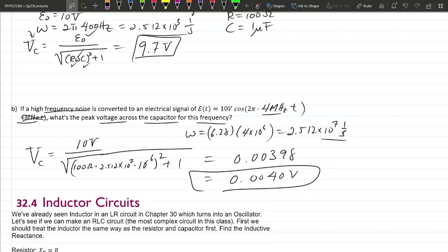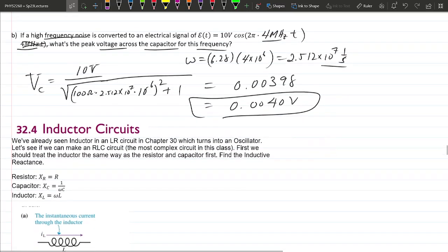It's used in every one of your devices, so that's why I want to make sure that this example is clear. Any questions? And if you did this with a high pass filter, the opposite would happen, where the high frequency signal will stay at like 9.7 volts, but then the low frequency signal will get reduced to like 0.00-something volt. You want this number to be low.